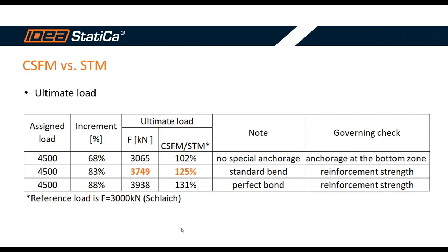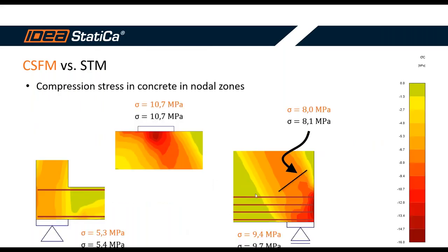But even in this example, it is written that it is assumed that in this zone B, the ties, the horizontal and also the inclined ones, will be with special anchorage at these ends with some hooks or bends.